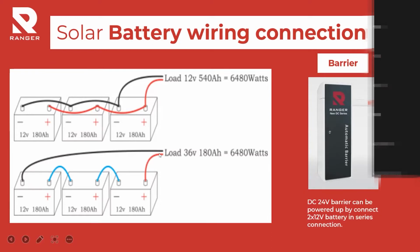Same as the solar connection, when you want to use series or parallel, for example this barrier, as I said before, uses DC 24 volt. So we can use two 12 volt batteries in series connection to power up this barrier.